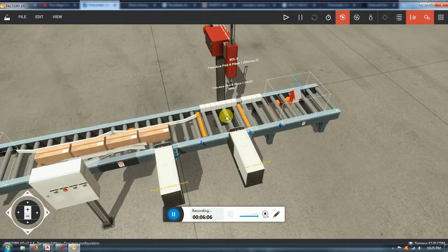The solenoid valves are grouped by manifolds, okay? A manifold is kind of like a block where the air gets in, and it's going to have different exits, each one for a valve, right? And we have to decide how many manifolds first, and second, how many valves per manifold.